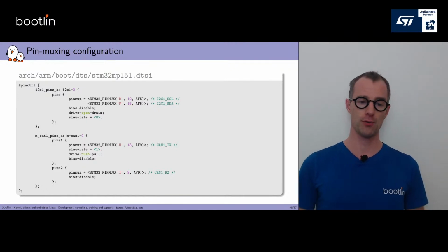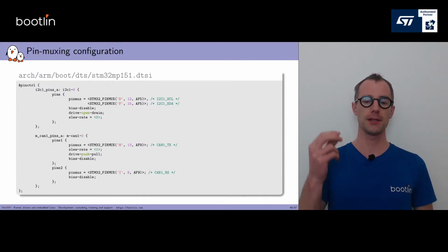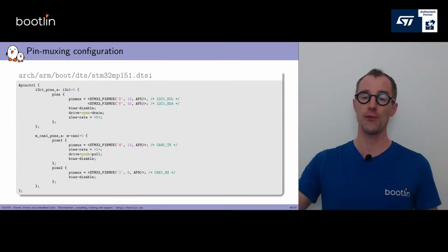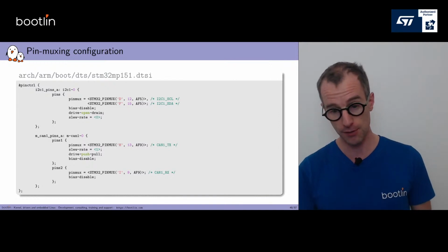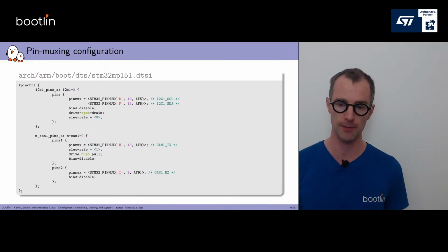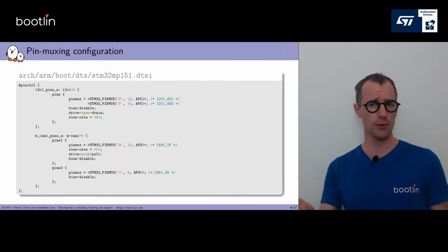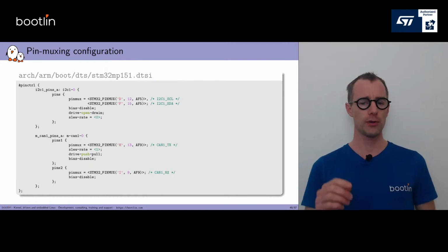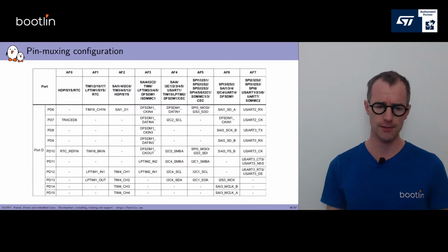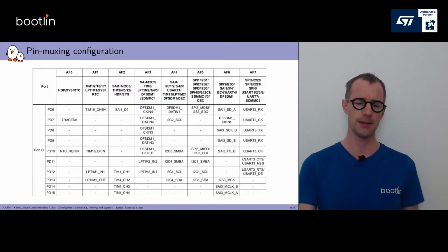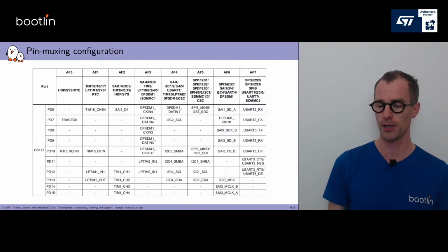Let's look at the first one for I2C. And it says that it configures 2 pins, pin D12 in function AF5 and pin F15 in function AF5 as well. And there are some very nice comments that tell us what this means, but you can also check it in the datasheet. If we look at pin D12, we open up the datasheet. It looks like this. It's a pin of port D, and in this table we can go to the line PD12, which is somewhere towards the bottom.